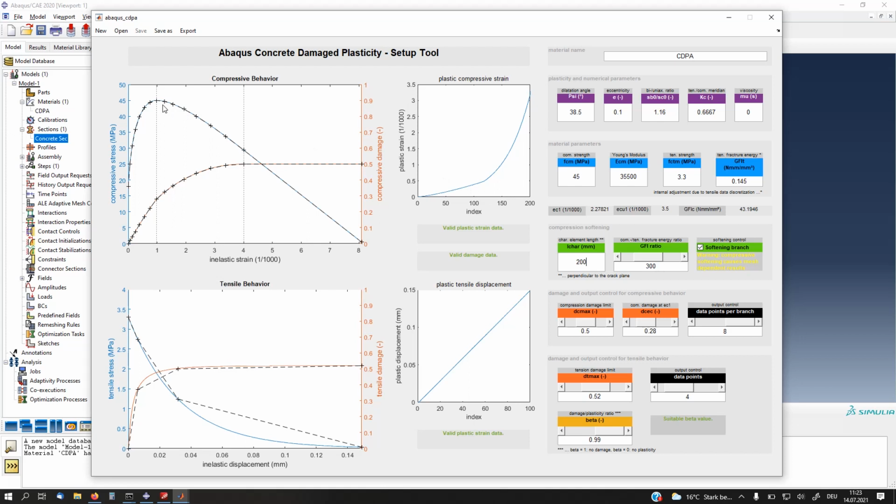then weight these values here so that you have a specific fracture energy for your compressive behavior. So this ruler tells you the tensile to compressive or compressive to tensile fracture energy ratio, which is about 250 to 300. And when you increase that value, you're going to notice that this curve shifts left, which doesn't mean that it's shifting left. It's actually shifting right.